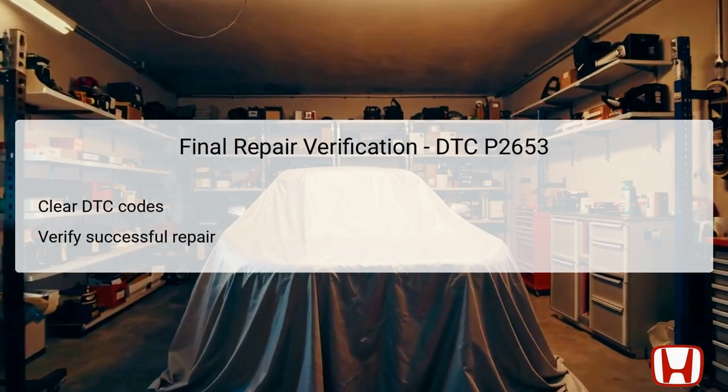It's essential to conduct a test drive to allow the vehicle systems to recalibrate and ensure that no further codes are triggered. Additionally, verifying that the engine runs smoothly without illumination of the check engine light confirms a successful repair. This verification step is crucial to ensure that the vehicle operates efficiently and adheres to performance standards.